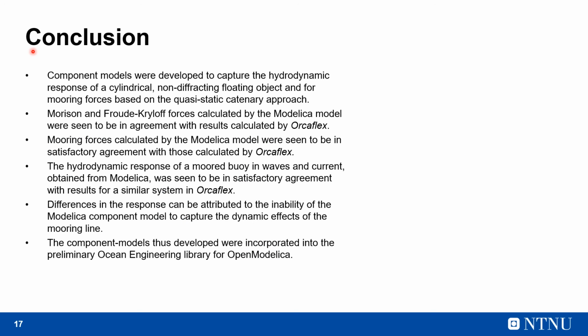Having looked at the simulation results, we come to the conclusion that the component models developed capture the hydrodynamic response of a cylindrical non-diffracting floating object and the mooring forces based on the quasi-static catenary approach. The Morison and Froude-Krylov forces calculated by the Modelica model were seen to be in good agreement with the results calculated by Orcaflex.